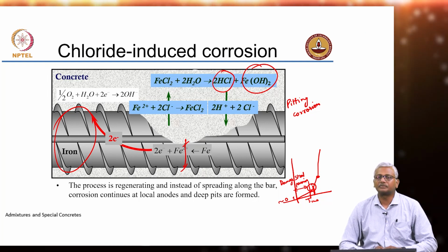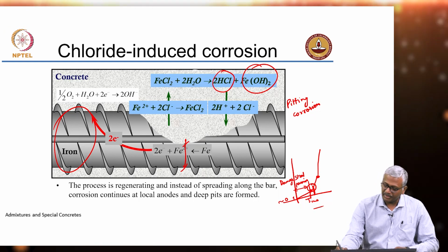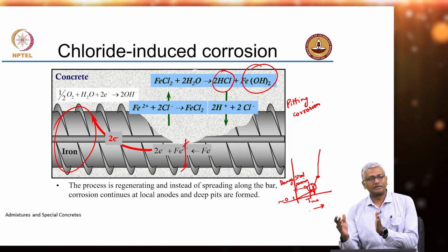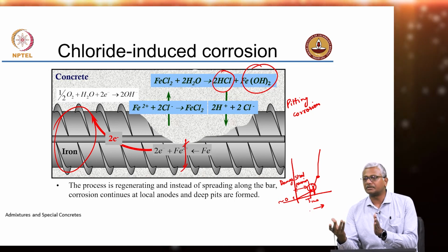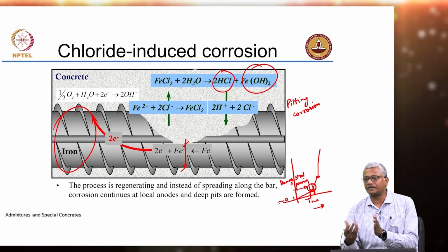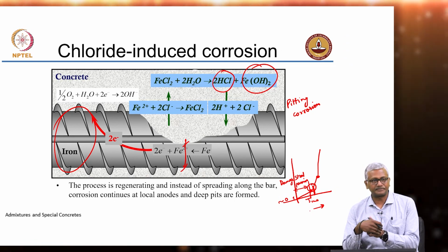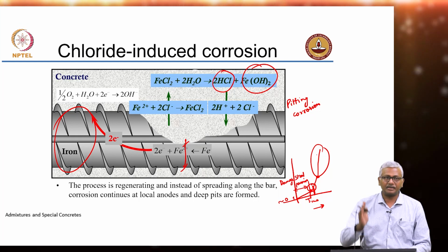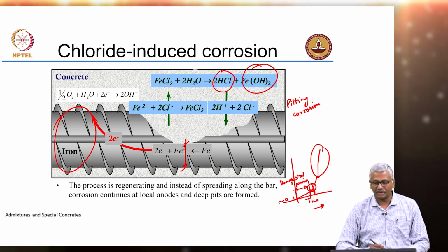Okay. But the problem is when it starts getting into this region beyond the passivation, the properties become unpredictable. The extent of cracking starts dictating the rate at which your chlorides come in, and because of that cracking, the later age damage basically increases significantly. Okay.